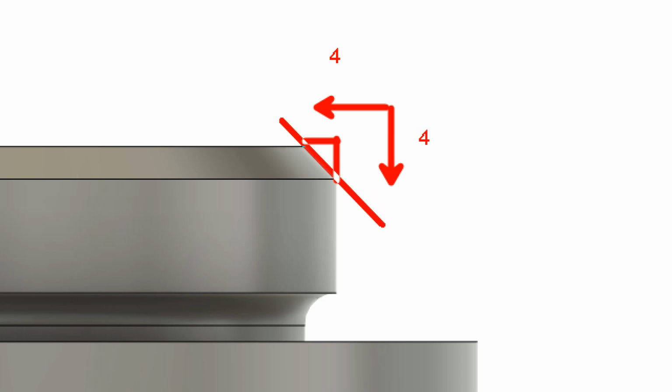All that means, if that wasn't completely understood there, it's going to be 45 degrees if it's an equal distance chamfer because this was square before, right? It went in at 90 degrees. If we're going in 4 inches this way, let me type that. My handwriting's horrible. If that's 4 inches that way and 4 inches this way, 4 inches down, that's going to create a 45-degree angle from what was a 90-degree angle.